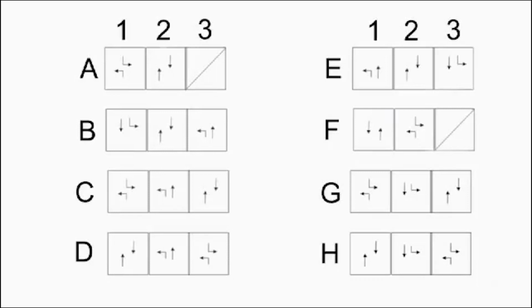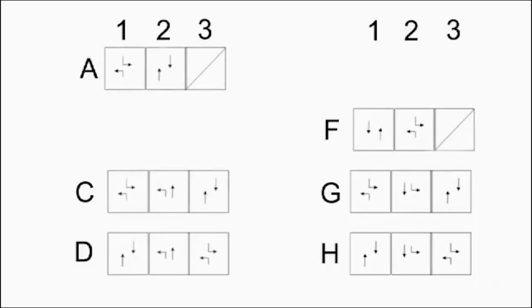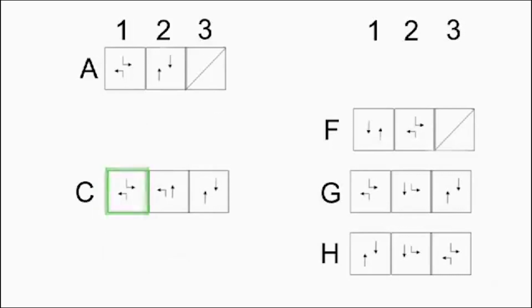So you have 8 states, which are the phase pairs, and 16 sequences. You can have less. Like for instance, if you say that in your city you don't want to have lagging left turns, for example, the sequence E goes away, sequence B goes away, sequence D goes away, and the state machine has to pick from any one of those depending on actual demand out in the field. No common cycle length, no transition, no wasting green time by dwelling on the main street green. You serve the traffic purely based on demand.